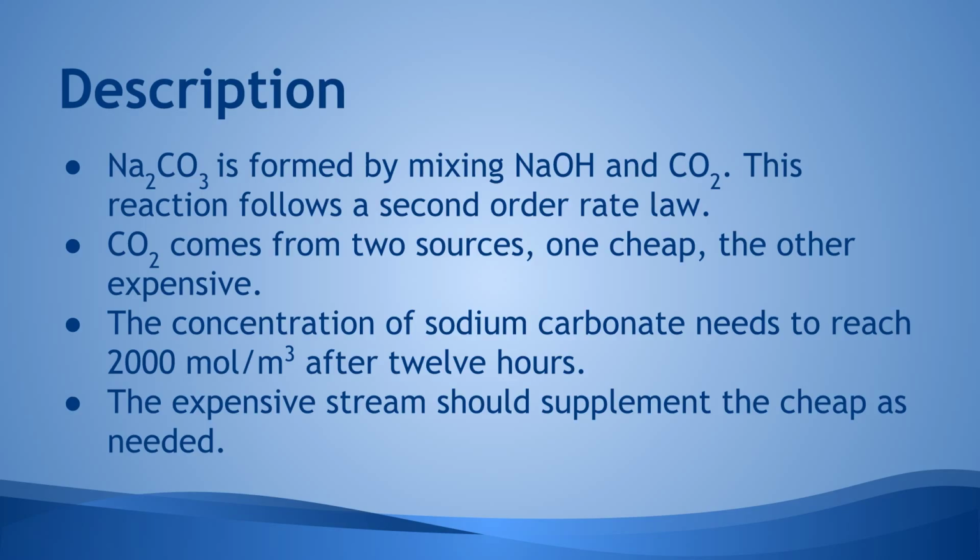We were able to get the carbon dioxide from two different sources. One is extremely cheap. It is from a cogeneration power plant that is nearby, and it's basically free carbon dioxide in that sense. However, that carbon dioxide is not sufficient for what is needed in the time frame that is necessary to react away the sodium hydroxide. The sodium hydroxide needs to be 80% reacted after 12 hours in order to meet the needs of the industry further downstream from there. And so a Praxair trailer full of liquid carbon dioxide is rented in order to supplement the carbon dioxide from the cogeneration plant.